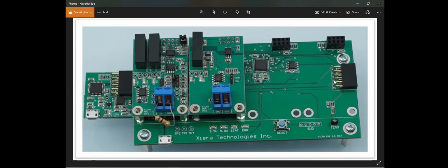Now, as part of the development and prototyping environment, we also included these larger boards. The large board is our evaluation board, which hosts these small I/O modules, which are swappable and flexible. We support many standard I/O signal formats: 0 to 10 volts, binary 0 to 10 volts, 4 to 20 milliamps, reading thermocouples and temperature sensors. We can output pulse width modulation signals, or just voltages, or the whole range of typical control signals that you see in the industry.